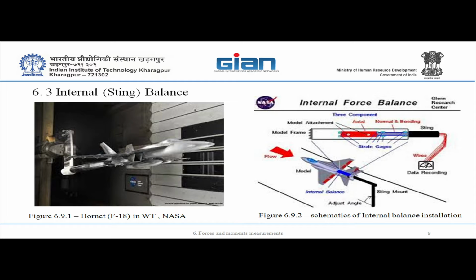Usually for normal force they use two strain gauges. That's the minimum. When they use two cells and my center of pressure location is at one of them, it will deteriorate, instead of being in the middle. That's why, preferably, as in the example I'm showing later on, they have at least 4 strain gauges for each component, so it will be less sensitive.